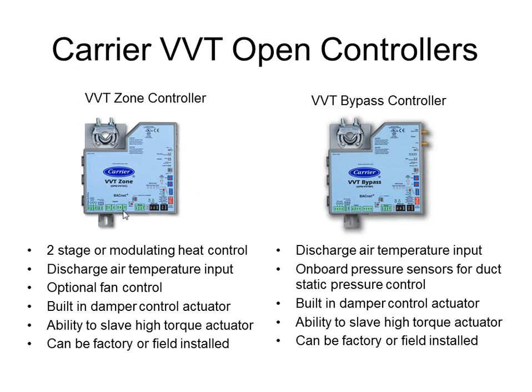So you just go through a question answer of saying, hey, you have hot water reheat that's modulating. You are a size 1600 zone damper, something like that. And it is all set up to run, all set up to communicate with the RTU-Open controller for the proper VVT system. So that's what Carrier can offer.